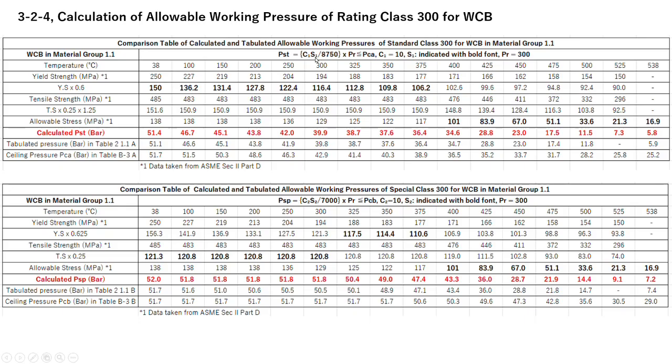So S1 value is something considered. So temperature is indicated 38, 100, 150 like this temperature. So yield strength and tensile strength. So data taken from ASME section 2 part D. So yield strength data assigned here. So tensile strength data right down here like this.